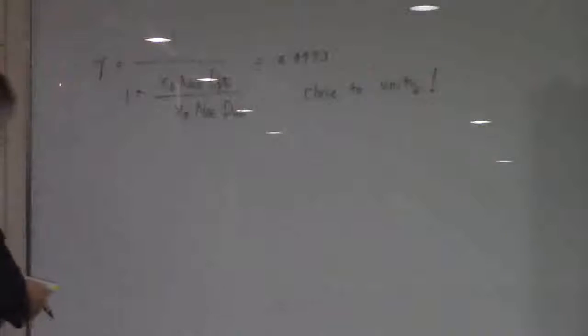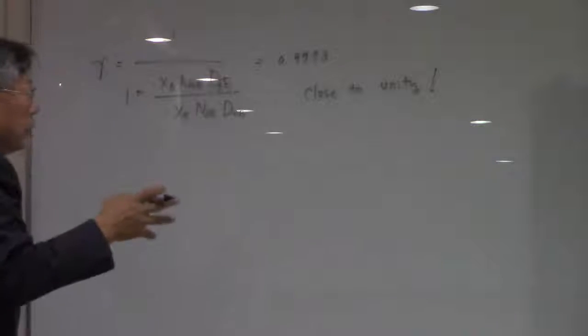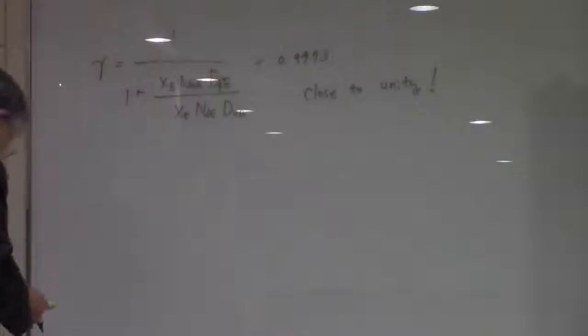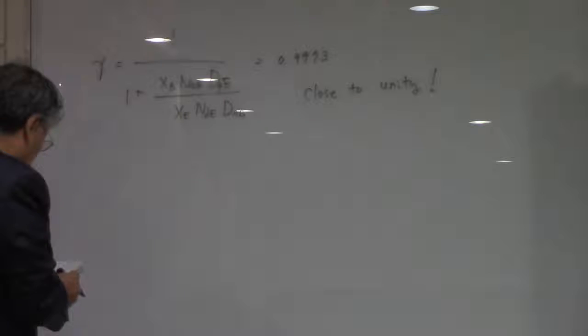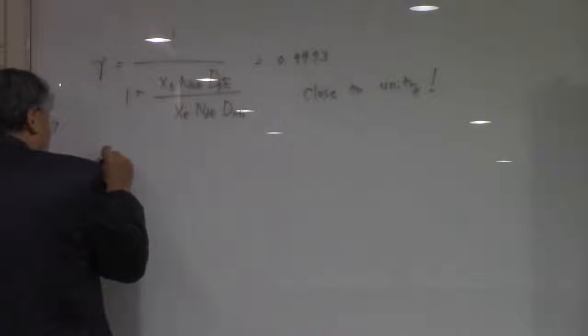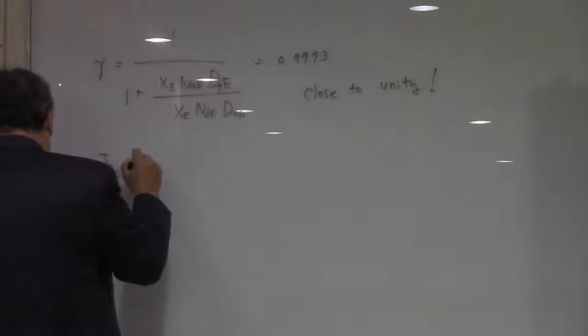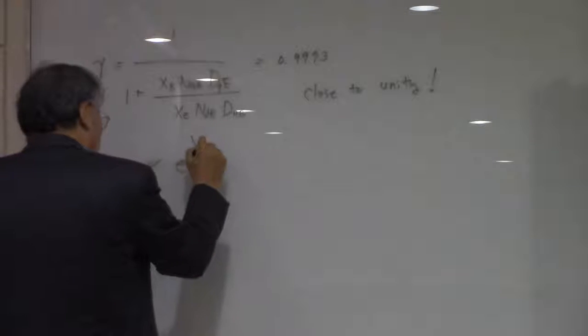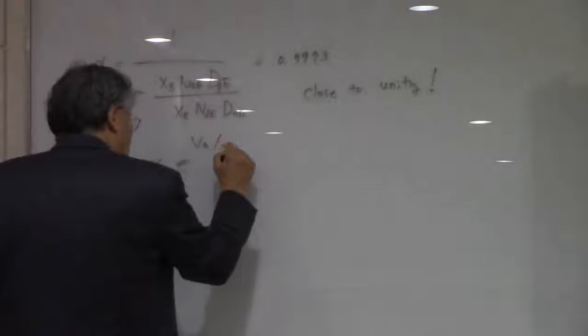Okay, and then the third part, the emitter-base space charge region recombination. We had an equation where JSC is going to be proportional to e to the VA over 2 VT.